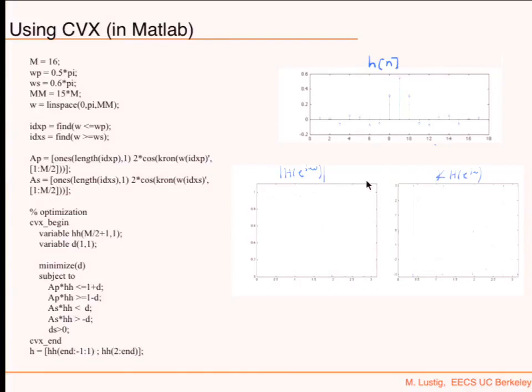It's useful to take 127. Yes, it is possible to prescribe such constraints. If you need to, then you need to go to these tools and figure out how to do them. Okay? But it is possible, and it's actually not very hard to do with today's newer methods. And you can also prescribe really complex types of filters in this particular way, whereas in the Parks-McClellan algorithm that is written in the book, it's really, really hard to prescribe these complex constraints.